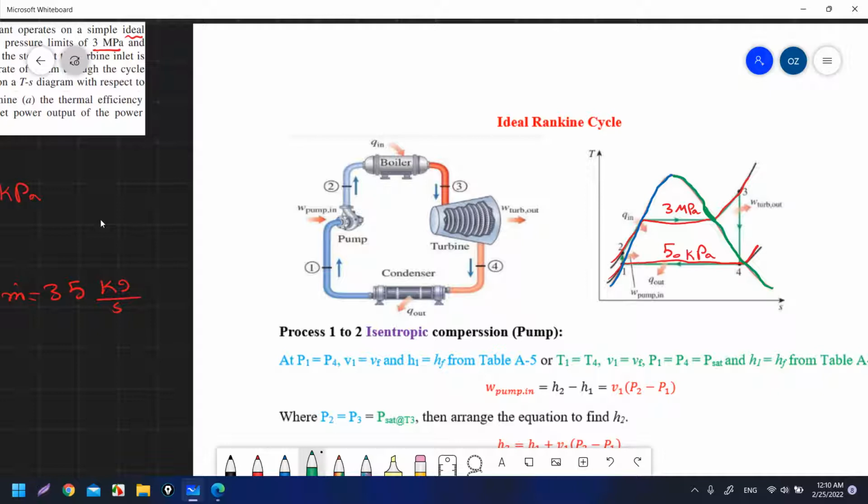Because in the Rankine cycle, usually stage 4 is a mixture, or a saturated vapor on the green line, or it is a superheated state. Okay, and usually if it is a mixture, the quality is above 0.9. But approximately, sometimes in the question you will have 0.8, sometimes you will not have anything like this. But if you don't know the numbers, you haven't solved yet, so draw it like this.